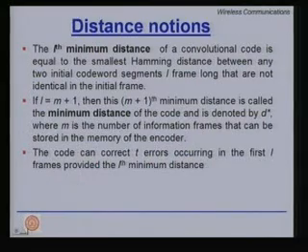A convenient measure is the Hamming distance between the two paths. If all the paths are very different, then a few errors introduced by the noise will not make one path look like another path in the trellis. That is, you will not mistake one bit sequence for another. So, we need a distance notion to tell how different two paths in the trellis are.